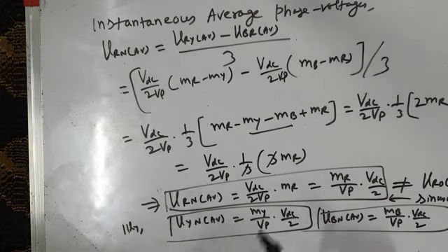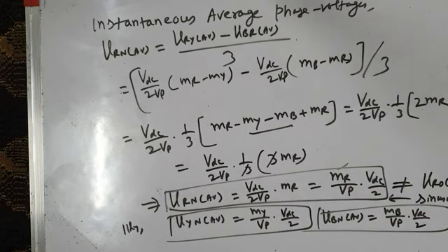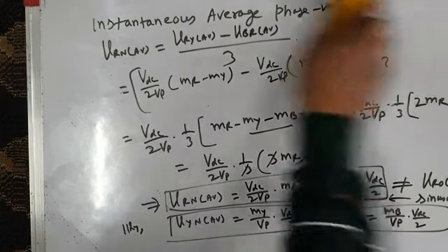Our line voltages and phase voltages are in terms of the original modulating waves, not the modified modulating waves. And since the original modulating waves are sinusoidal, our line voltages and phase voltages also are sinusoidal. In other words, this common mode signal does not appear in either line voltages or phase voltages. So the average inverter output voltage remains sinusoidal.